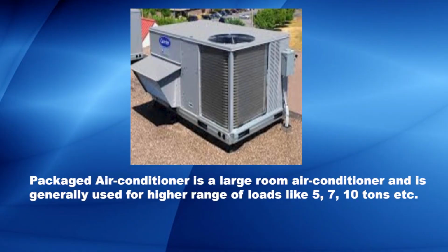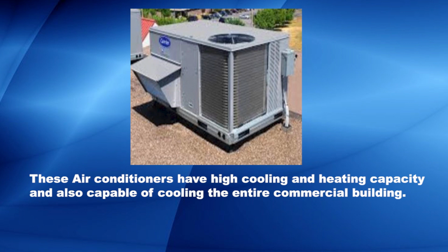Package air conditioner. Package air conditioner is a large room air conditioner and is generally used for higher range of loads like 5, 7 or 10 tons, etc. Package air conditioners are installed either on the rooftop or side wall of a building and generally used in places such as a restaurant, homes, telephone exchanges, and small malls. These air conditioners have high cooling and heating capacity and are also capable of cooling the entire commercial building.